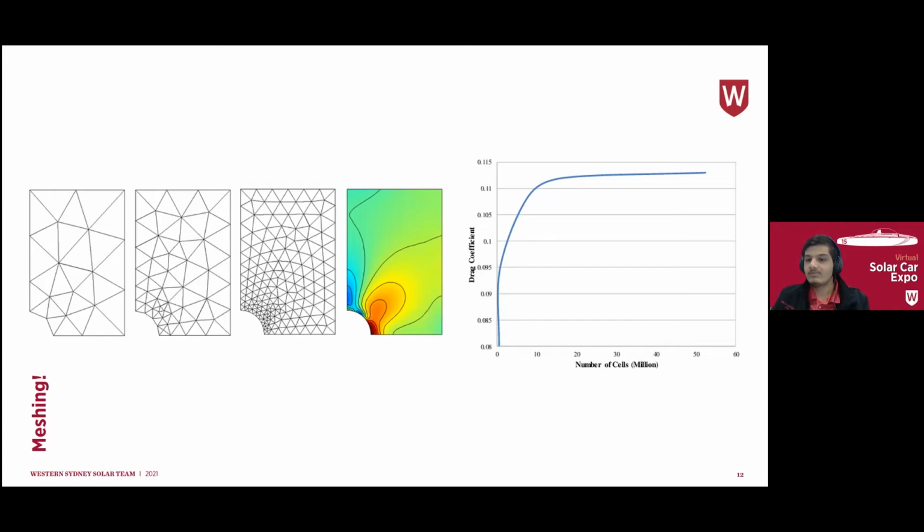This is why it is important to perform sensitivity studies. Using one representative part, you can conduct the simulation with various different levels of mesh density. Once the results stop changing too much, you have reached diminishing returns, and that is the level of mesh you should run to get the best results for the least computational resource. This is shown on the graph on the right as the point where the data levels out. Once you know this, all similar parts can be simulated under the same conditions and saves you a lot of time.